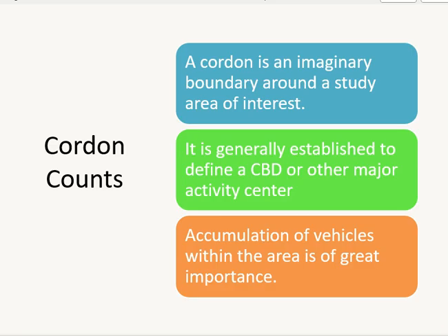So if you have a prominent feature, an important feature, which could be a highway, a river, a railway line, something like this, which is already at the edge of the area, don't avoid it, put it as part of your boundary. And the advantage will be that on this side of the boundary the crossing points will be very few. Got it? Clear?